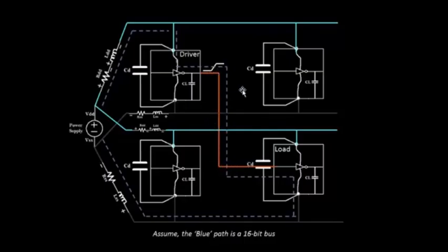And also it's not very feasible to put decoupling capacitors all over the chip. So some sections, some critical blocks are decoupled from the main supply using decoupling capacitors, but not each and every element. We can't do that, it's not feasible. Okay, so over here this particular line has to be taken care of by this power supply, and this power supply is sitting at a far distance from this line, so there is always a possibility of voltage drop. So what you see as VDD over here might not be VDD on this line, but might be something else. Let's try to see how.